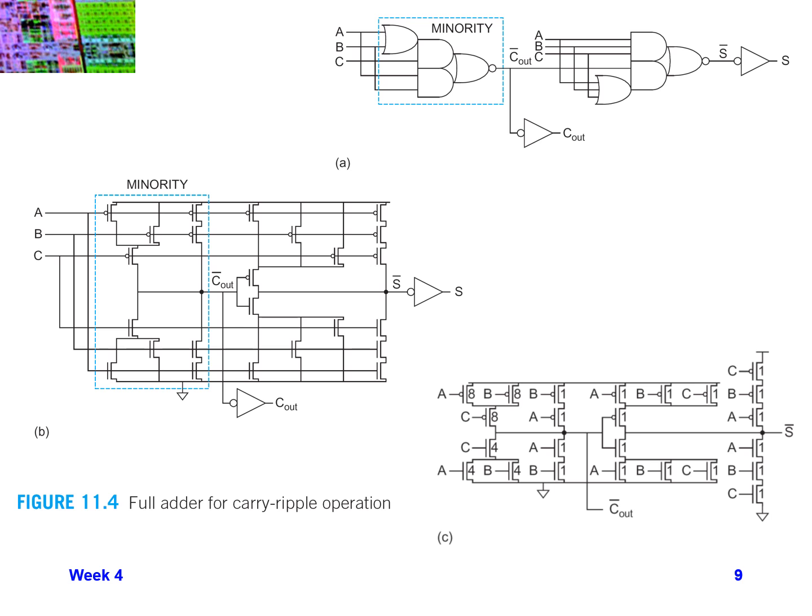If we do larger gates for the carry in, which are size 8 and 4 for the P and NMOS, the speed going from carry in to carry out bar is going to be a lot faster than if we use minimum size gates.